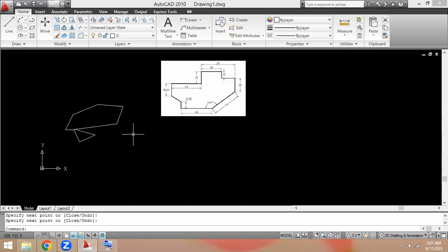So basically, go to draw the line. Before drawing the line, we have to set up the line properties. To set up line properties, as a practice, we should go with layers. I'm creating a new layer.